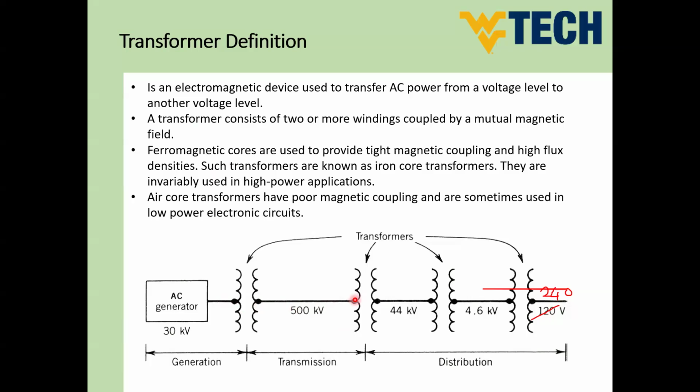And at the same time, guys, this would reduce the cross-section of the cable or transmission line used. Because if you need high current, for sure the cross-section area of the cable or the transmission line has to be high in order to transmit this high current. So this is very important, guys, to understand the feasibility. Why do we use transformers?